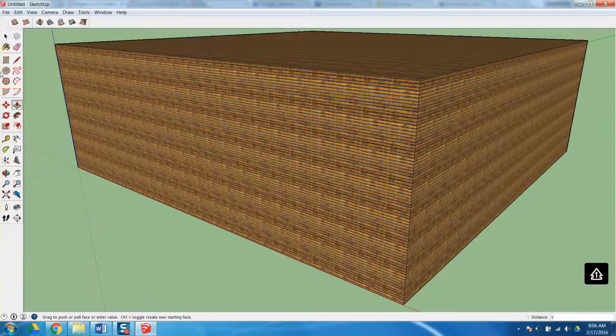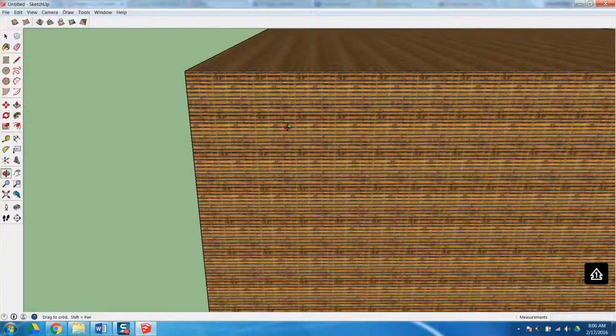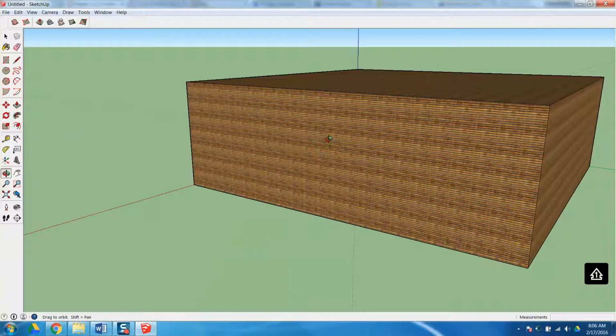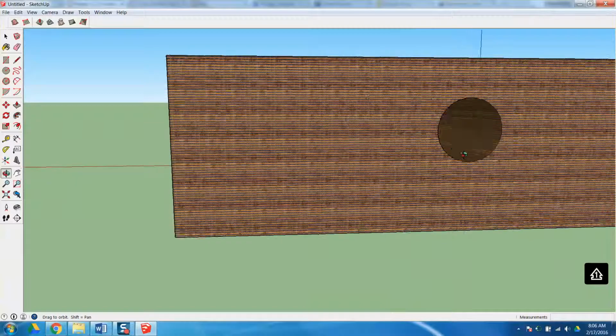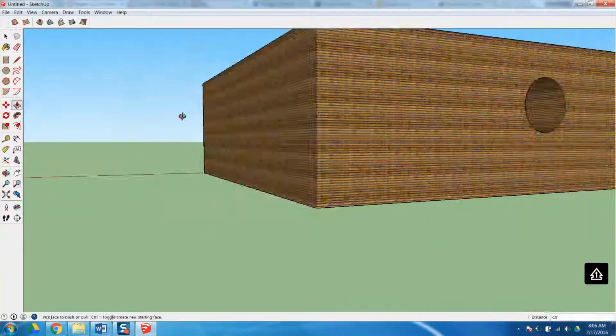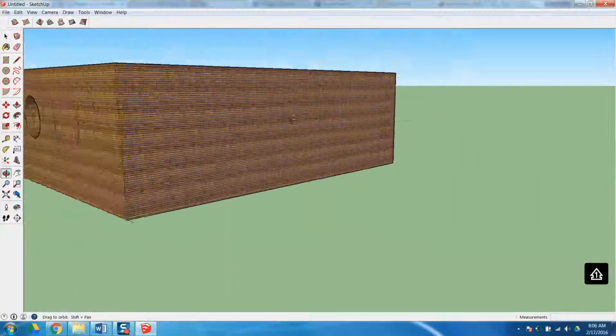Once you have a three-dimensional shape, you can also make different shapes within that, and you can push-pull those shapes to cut if you want to. So you notice I'm still in that particular push-pull, and if you select a face and roll over it where it says on face, I can click again and it cuts it all the way through. Okay, so I'll show that to you with the other hole.